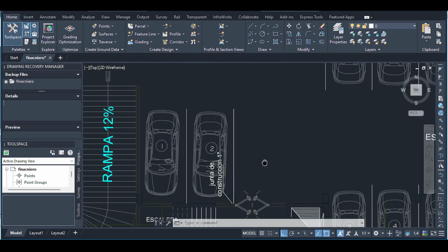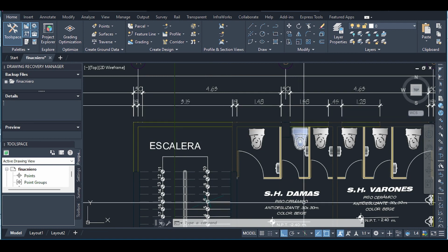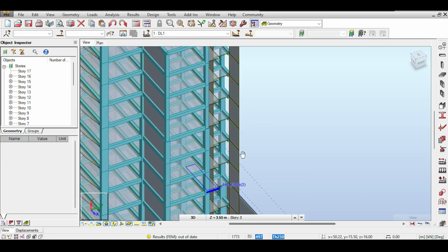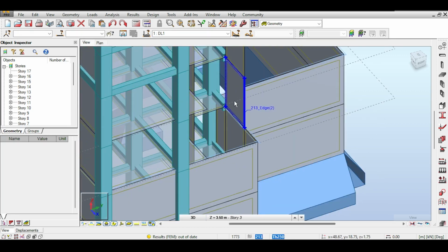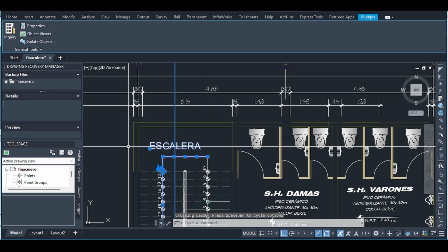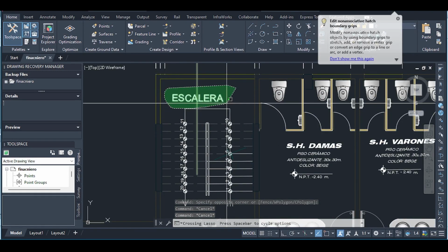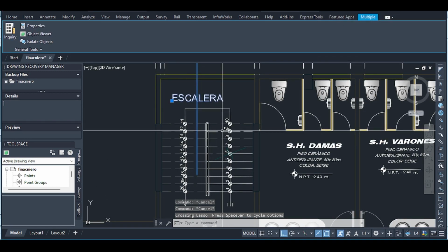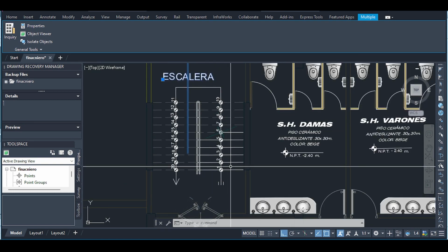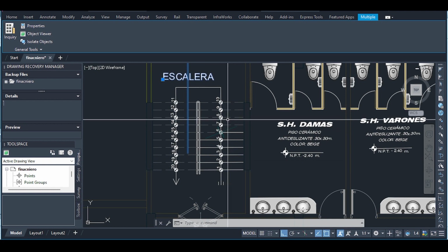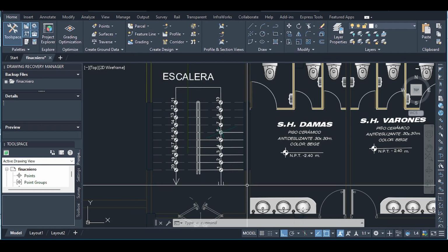Now in modeling the staircases, I am not really that accurate, but I'm also not inaccurate. What I mean by that is that usually when I model the staircase, I am interested in modeling the two flights, and I am also interested in modeling the slab here. And I know sometimes in some staircases, this intermediate slab is not at the middle point of the height. I can see it is, but even if it is not, even if I have unsymmetric flights, meaning, for example, 12 stairs here and 8 stairs here, I would still assume them to be symmetric to basically make my modeling life easier.